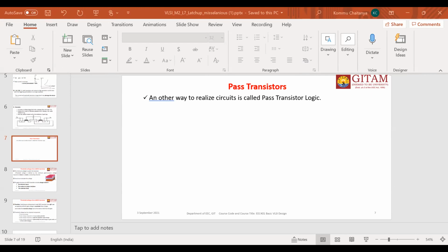Of course, these are the two conducting plates. There is a possibility of a capacitor here also. Okay, so here also there is a capacitor. There is a possibility of a diode. Here also there is a capacitance. Of course, we know that a capacitance will form here between the channel and this region. Like this, different types of capacitances and different types of diodes, all these things will be formed within the circuit itself.